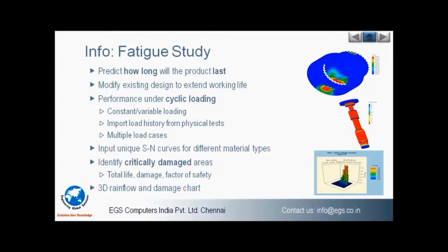Using the fatigue study, we can predict how long the product will last or what is the minimum life cycle of my product. When we modify the existing design, we can obviously extend its working life. And we can predict the performance under cyclic or non-cyclic loading, either a constant loading or a variable loading.